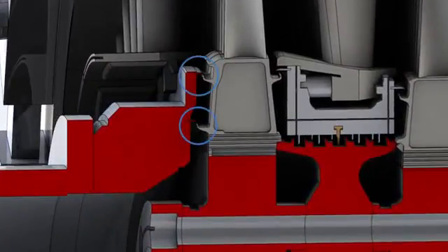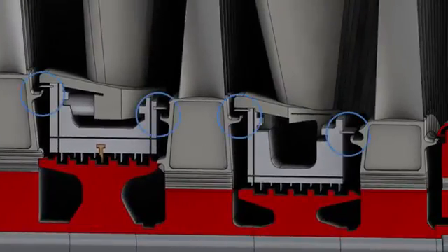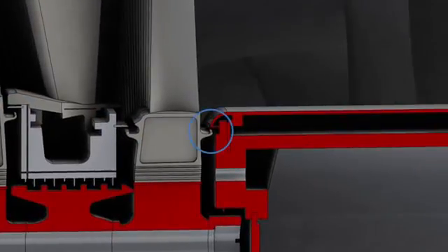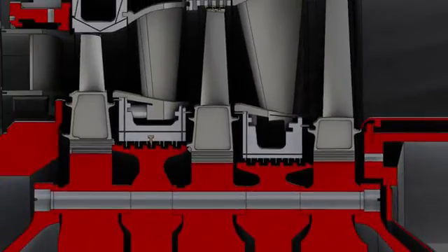Seals from the first stage nozzle support ring mate with sealing wings extending from the forward side of the first stage bucket shank. Also, seals from both sides of each diaphragm mate with sealing wings from both sides of each bucket. The seal from the exhaust frame mates with the sealing wing on the aft side of the third stage bucket shank. All these seals reduce leakage of the hot gases radially inward to rotor parts, improving turbine efficiency and protecting the rotor parts.